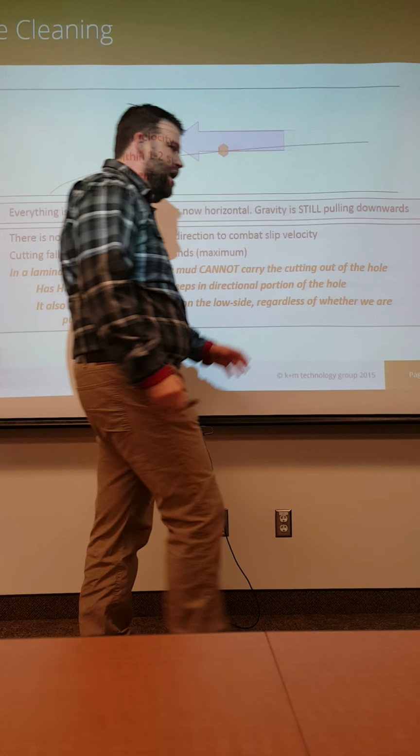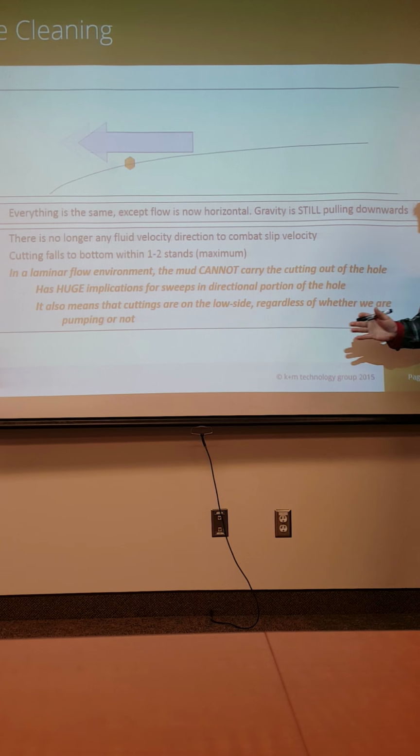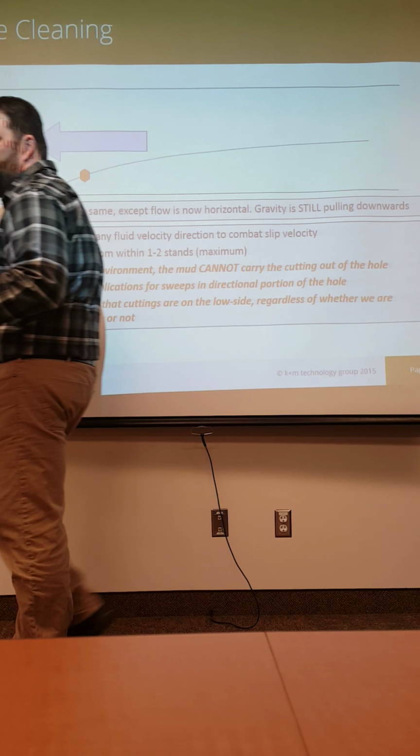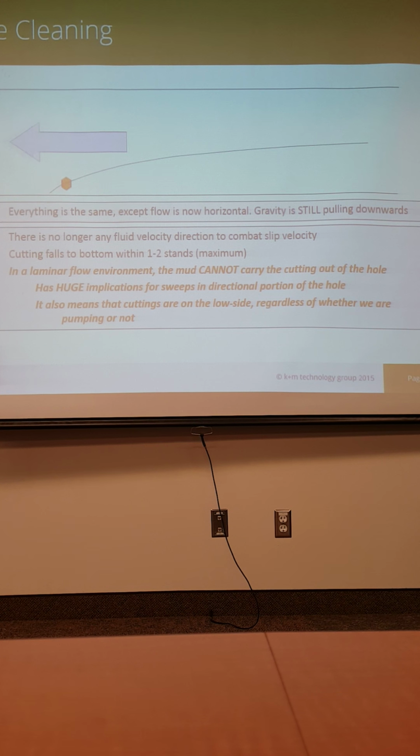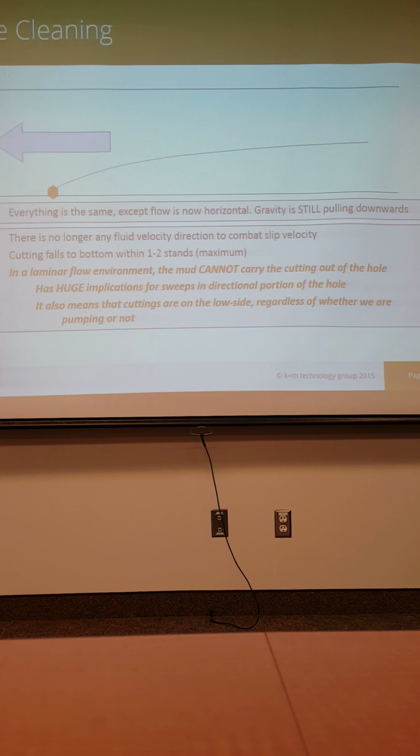Here's the scale of our problem in hole cleaning. High-speed angular velocity, amazing hole cleaning happens at 200 foot per minute. I can walk at 200 foot per minute. So here you've got your happy little dirt particle, and it's flying up the annulus at 200 foot per minute. And it's got to travel 30,000 feet.